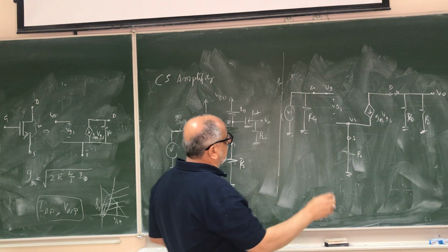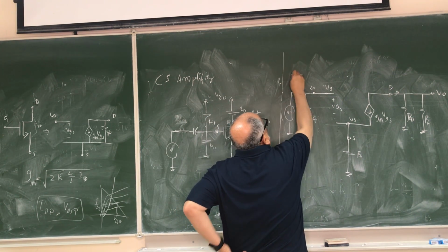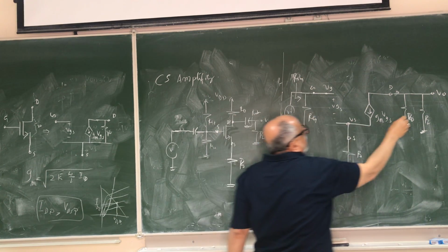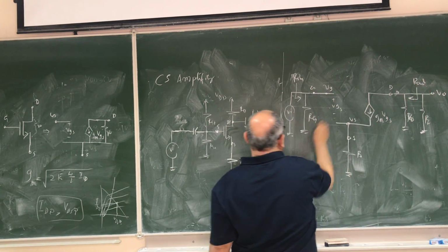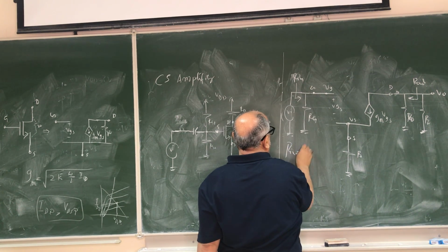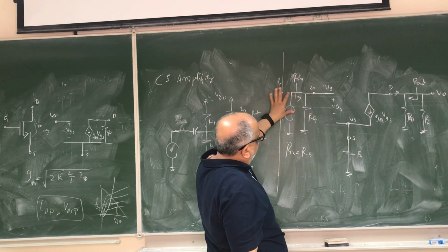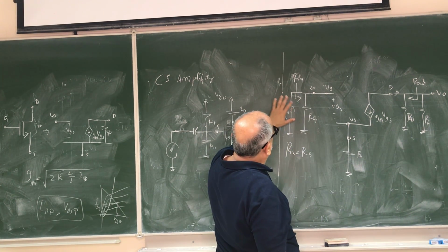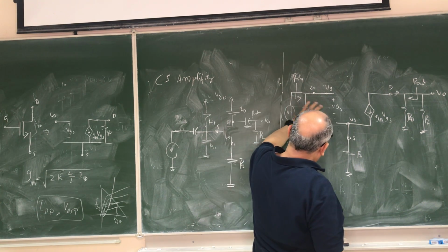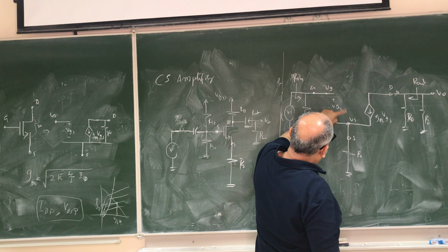From the input resistance and output resistance point of view, we have Rin here and Rout there, right? So Rin is equal to R. It is the same. Now to find Rout, we short this. If we short this, this potential will be minus VS here.